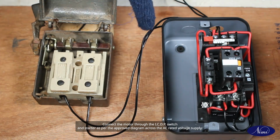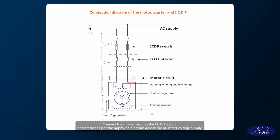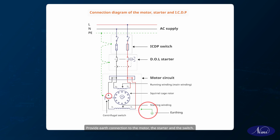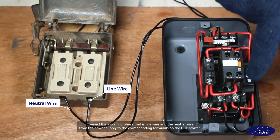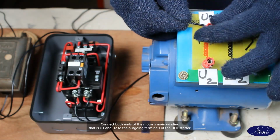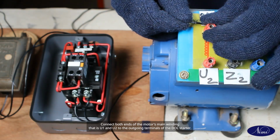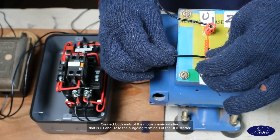Connect the motor through the ICDP switch and starter as per the approved diagram across the AC rated voltage supply. Provide earth connection to the motor, the starter and the switch. Connect the incoming phase, that is line wire, and the neutral wire from the power supply to the corresponding terminals on the DOL starter. Connect both ends of the motor's main winding, that is U1 and U2, to the outgoing terminals of the DOL starter.